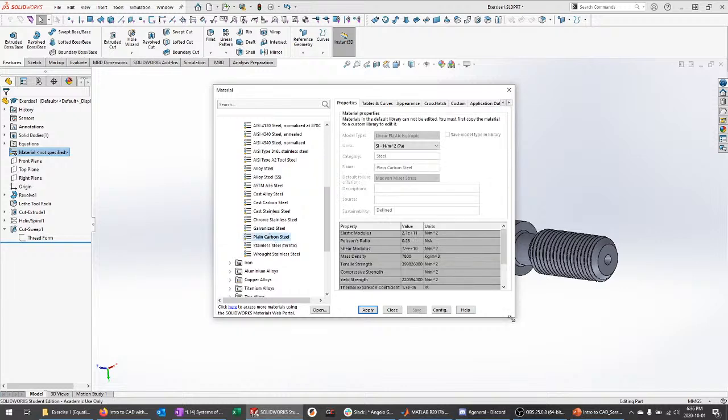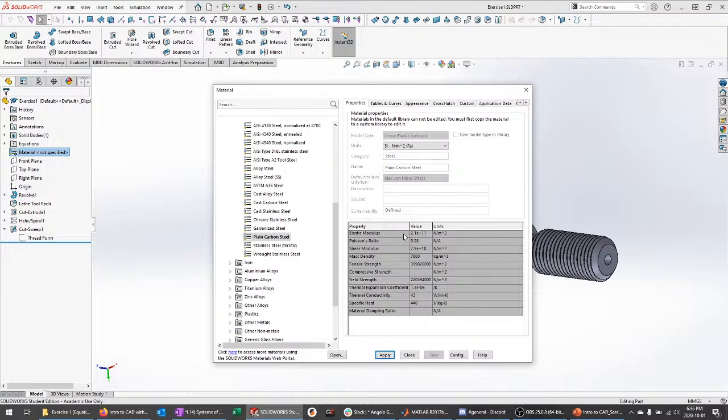You can see here, it's not just the names of the materials, but it's actually got important material properties. Elastic modulus, which describes the stiffness. Poisson's ratio. If you care about estimating the mass of your part, mass density is in here. Thermal conductivity if you're doing some thermal FEA, thermal simulations. So it's got preloaded a bunch of different material properties, and that makes it really convenient. So I'm just going to select that steel, hit apply.